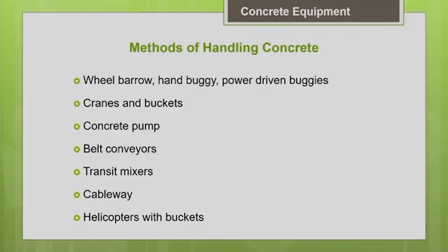There are different methods of handling the concrete, starting from very simple methods like wheelbarrows and hand buggies, to advanced methods like concrete pumping and belt conveyors. So there is a range of options available. Depending upon your job productivity requirement, your placement rate needed, and how much horizontal or vertical reach you need to cover, you have to make the choice of the method of handling the concrete.